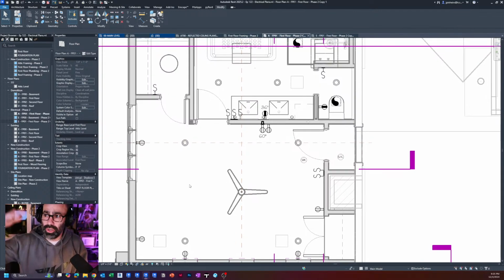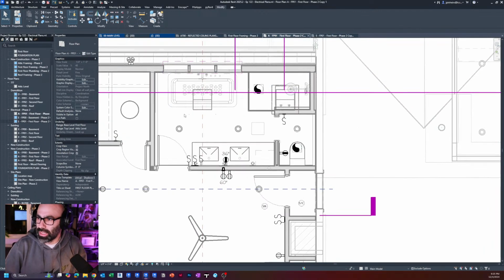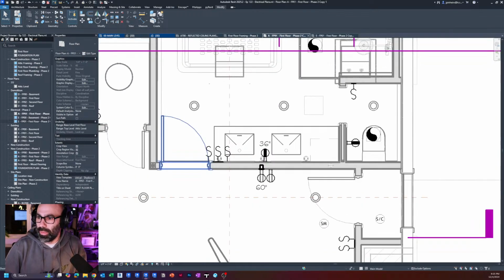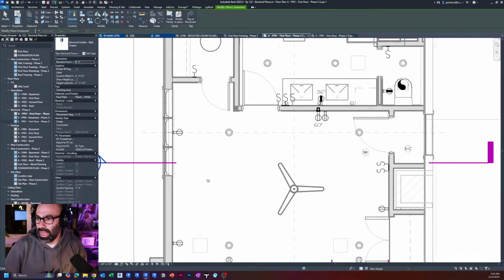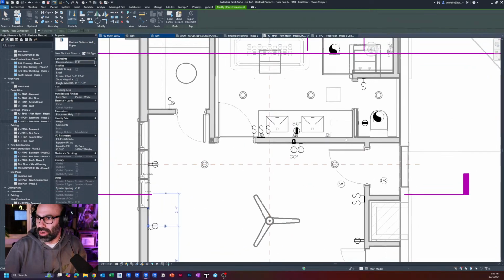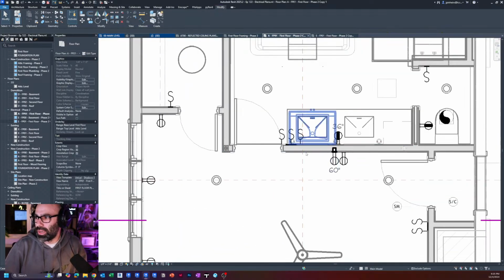But you'll notice I turned off the surface patterns for the ceilings. Again, that could be something you want to keep on, or you could use a filter to turn off the chipboard one or whatever it is, depending on your project. But that's kind of what I have set here. And so, placing them, what's nice is I basically create one of these views, and I'm literally just creating similar views and adding stuff around as needed, right?